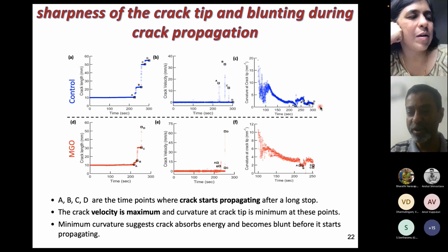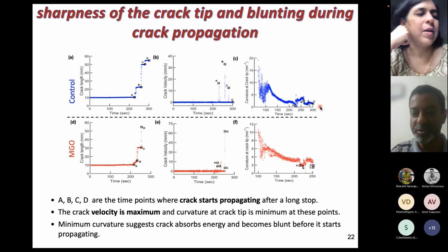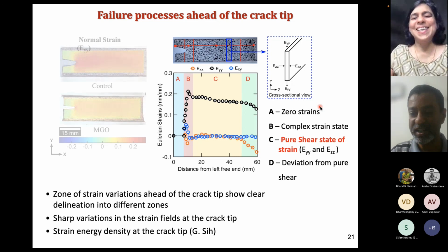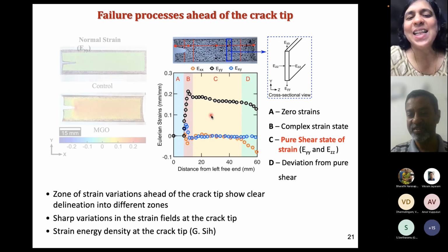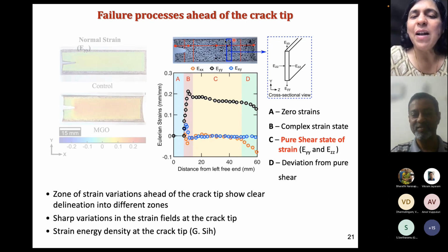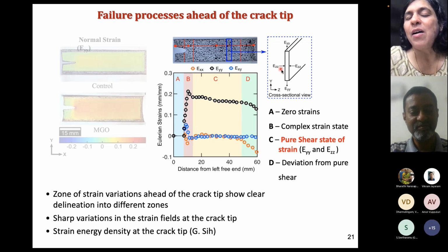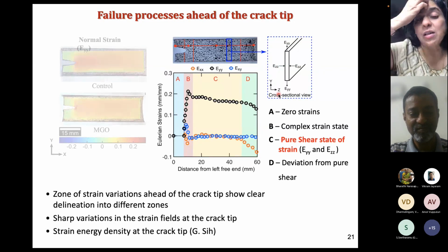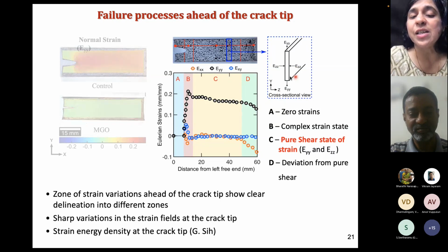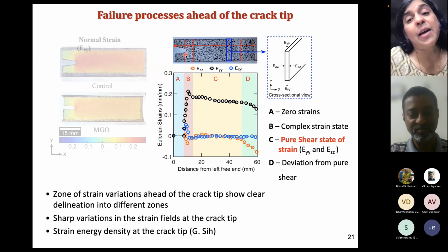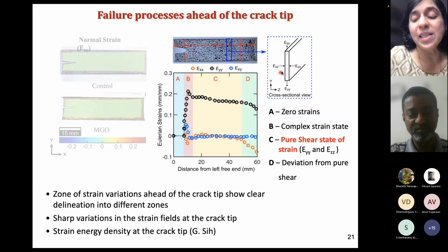Amol Pupuluri has asked, would you like to know how GC is calculated? Also, why is the test called a pure shear, as I can see a mode 1 test there only? Yeah, so that's why we put this figure, it wasn't very clear, I think, when you started. When we are tearing this film, we are not able to have eyes on the ZZ direction. But these are called pure shear because you create this pure shear region in this YZ direction. This is like a mode 3 in the YZ direction.